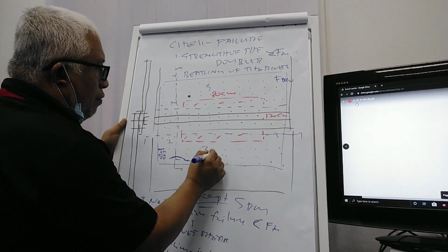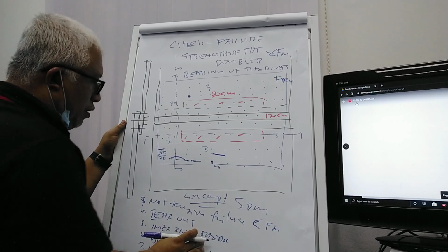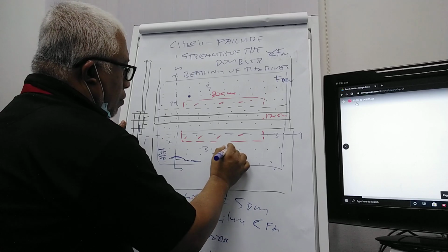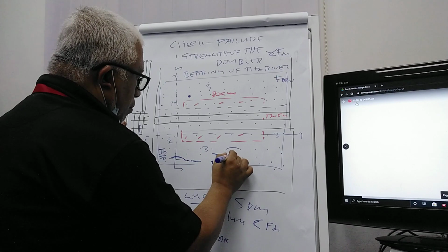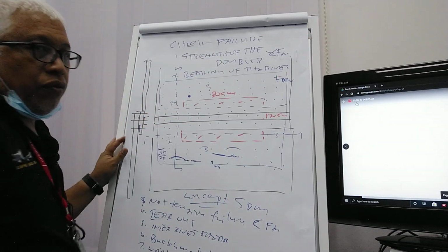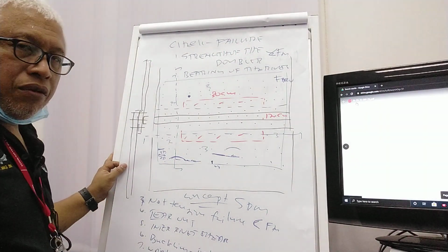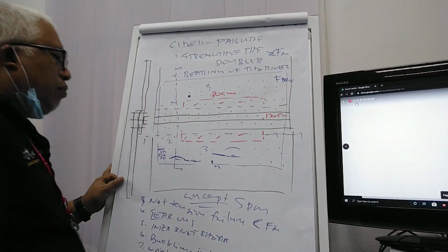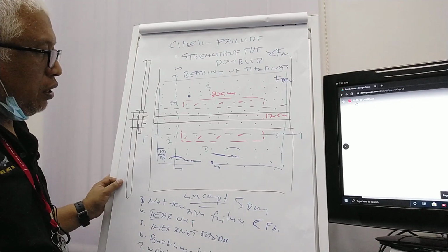And then between rivet to rivet, there also may be shear off, inter-rivet shear. Then if we get buckle between the fasteners, this is inter-rivet buckling. If you get wrinkle between the rivets on the skin, this is wrinkling. So those are the checks that we need to do. Before you do a check, the check has to be done through the analysis, through the calculation. So before you go to calculation, you need to determine the engineering values for you to use in the calculation.